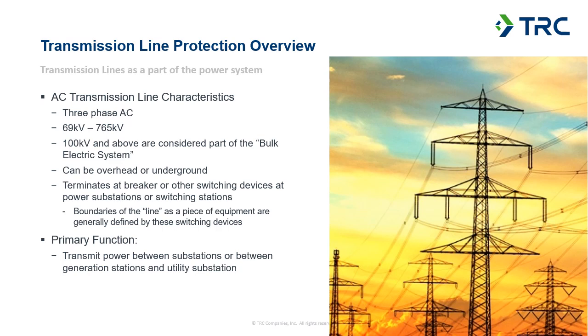That's generally anything 100 kV and above. You may also hear the term bulk power system. That's a little bit more complicated term to define because it's not really just based on a voltage cutoff, but is another term that describes basically the most critical portions of the system used for large power transfers throughout the power system.